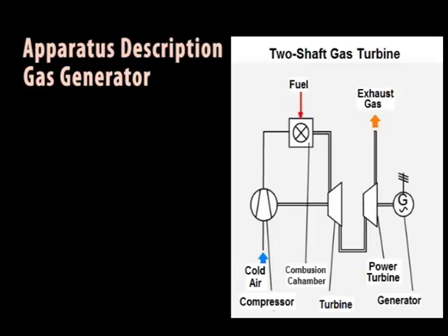The air drawn in is injected into the light alloy spiral housing by the compressor wheel rotating at high speed between 60,000 and 125,000 revolutions per minute. The speed of the air is converted into pressure. The compressed air is further slowed down in the diffuser and then fed to the combustion chamber.